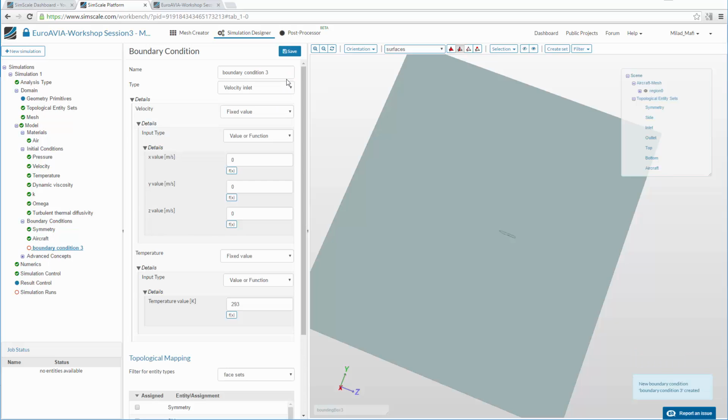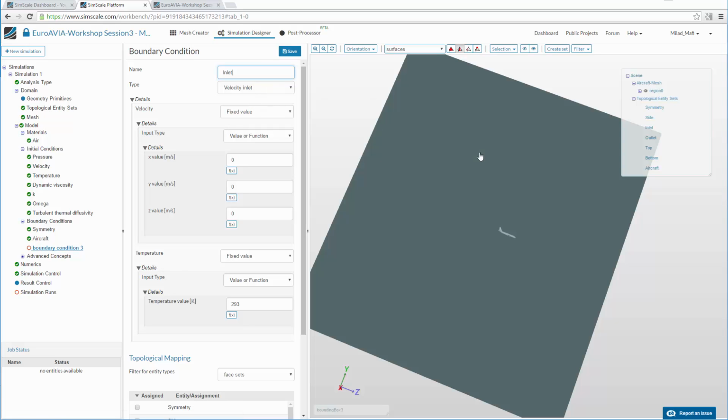Next boundary condition we have to add is for the inlet, and this is a little bit more complex than you may first see because, especially for compressible simulation, you can really run into convergence problems for high inlet velocities. And there is a very smart trick that is called ramping. That means you are not starting with the full flow velocity you want to simulate, you start with a smaller one, and then you can step by step with every iteration increase this value, and this will damp numerical problems and help you to reach a faster and better convergence all in all.